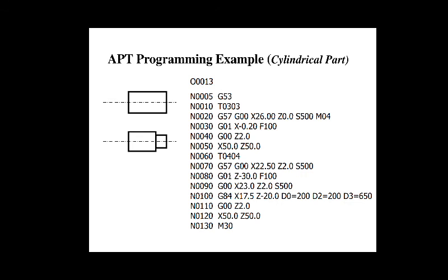And one last time I am going to repeat it: it is good practice to increment each block number by 5 to 10, to allow additional blocks to be inserted if future changes are required.